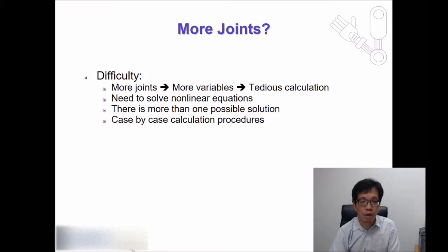However, if you try to solve everything backwards, like you try to find out all the coefficients for individual joints using inverse solving procedures, you're going to find it is going to be difficult. As we talked about earlier, there is no systematic way to solve the individual parameters. In particular, if you have one variable, you need to have one equation. If you have 6 joints, you might have 24 variables. It is not very likely that we can solve all the 24 variables.